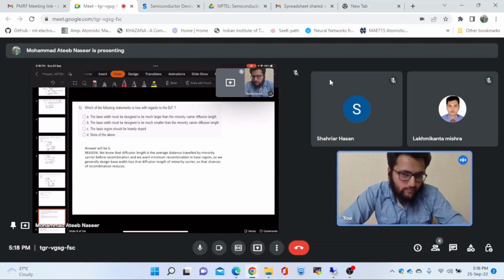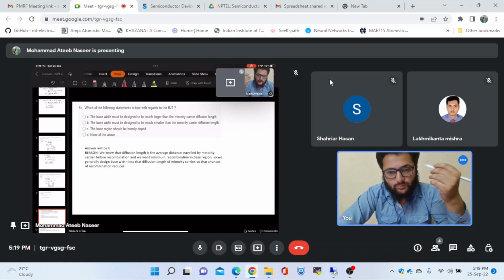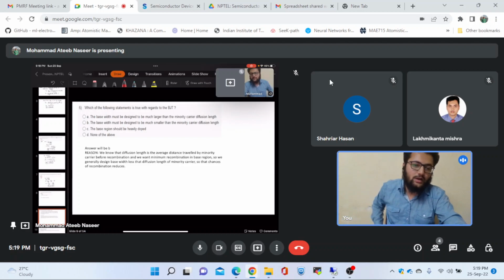A large number of materials are being investigated currently, and an active research field is two-dimensional materials, such as MoSi2N4, which is one such example. It has holes which are much more mobile as compared to the electrons. So it all depends on how the E-k, the band diagram, looks. The effective mass and everything is a property of the material.